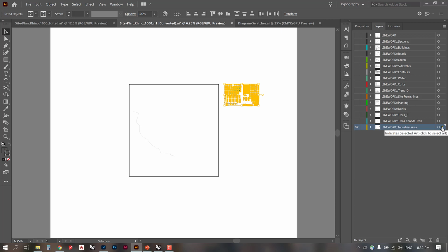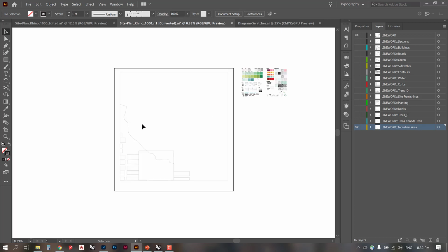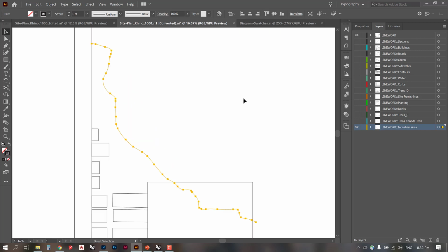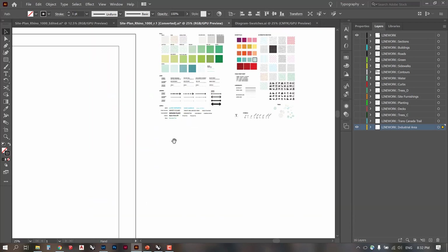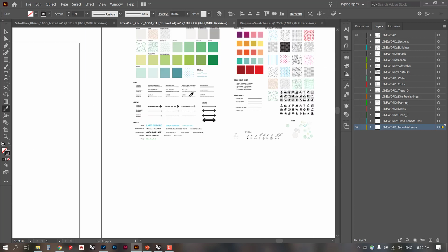They come in at the layer that you're working on. So I will just drag that little square up onto the top layer, and I'll just place it there for now. So again, if I'm looking at this boundary, I might want to select a line that looks like a property boundary. So I'm going to go over here and use the eyedropper tool to grab this property boundary right here.